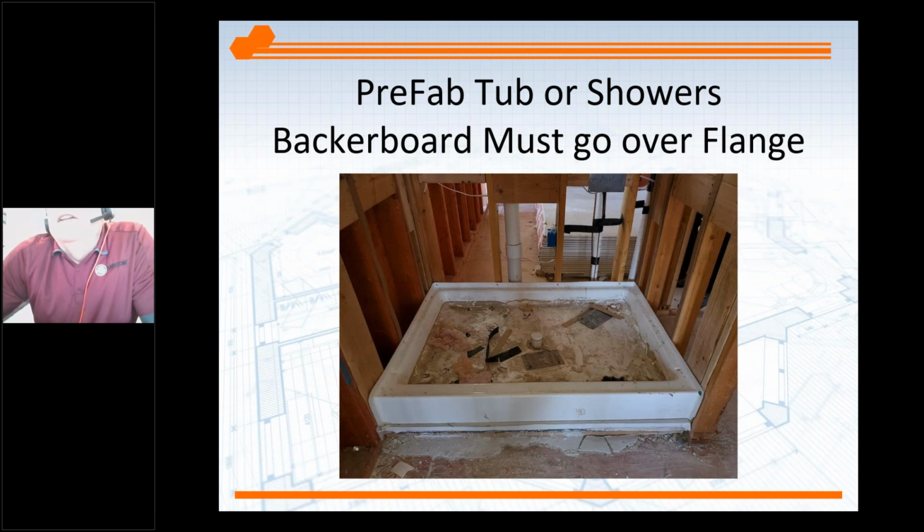You can see here they actually shimmed it out already, but they shimmed it out before they put the pan in. And a lot of times we see the board set on top of the pan or even a gap in there, and that's going to be an issue and a problem for leaking. And it's always best to get the full sheet down there. You don't want to try to patch in little. I mean, if you have to, there are some ways we can do that, but it's best to get the backer board over the top of those flanges.